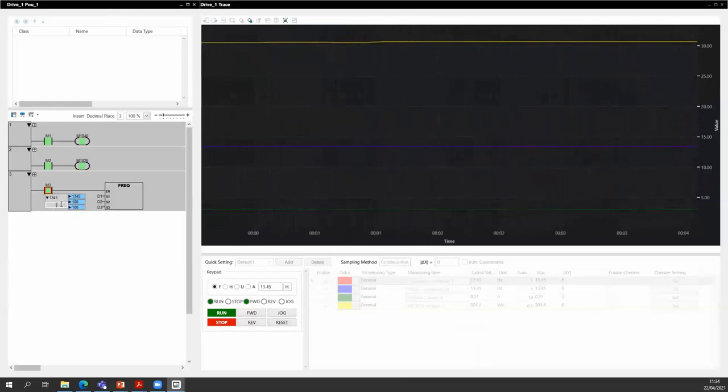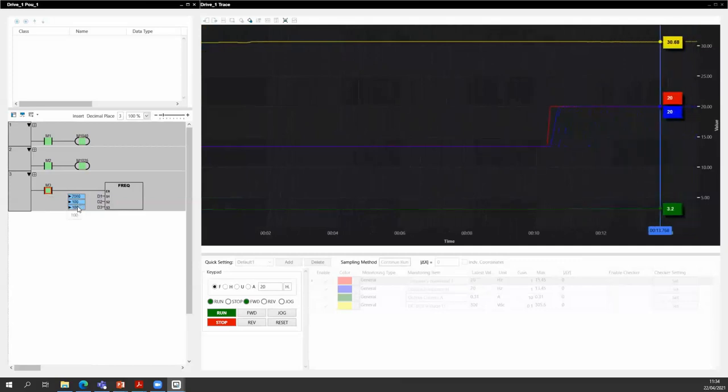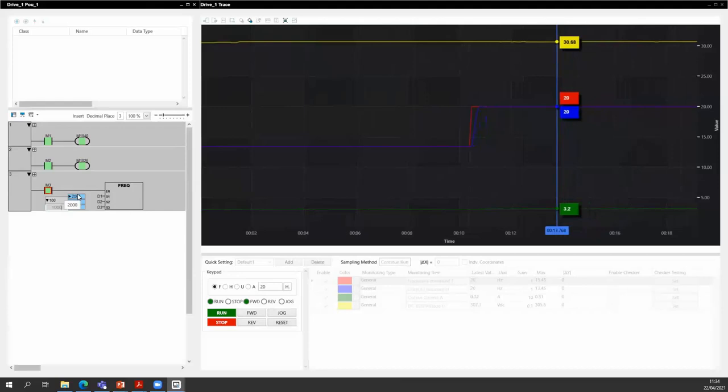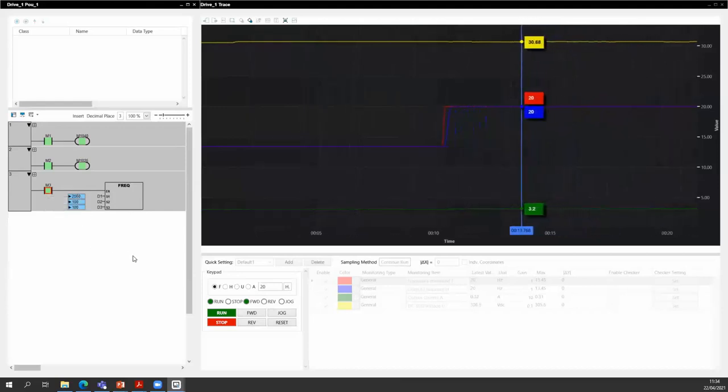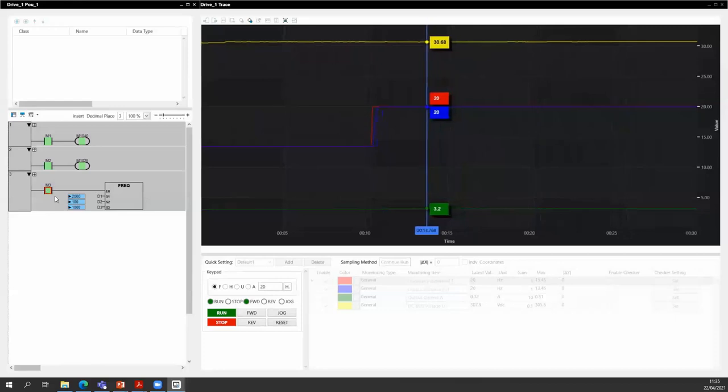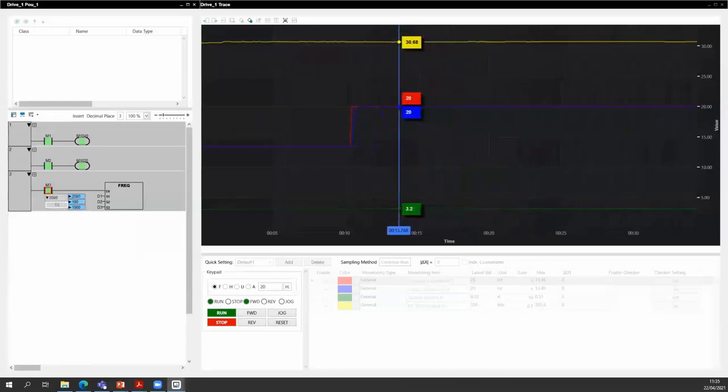I can change this to 20 Hertz. So I set here 2000. And then you can see it here. I can change the deceleration ramp to be much slower. So I can set it to 10. And, yeah, so now it's okay. I can give it a frequency command of 10 Hertz.